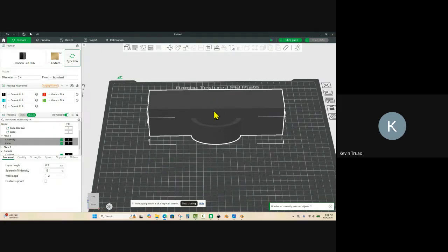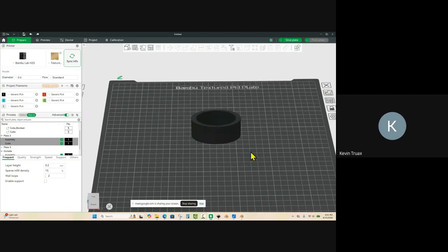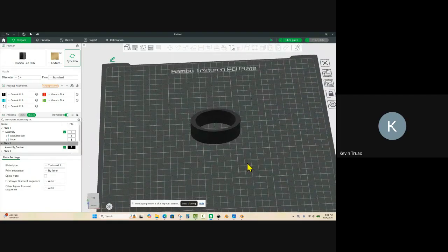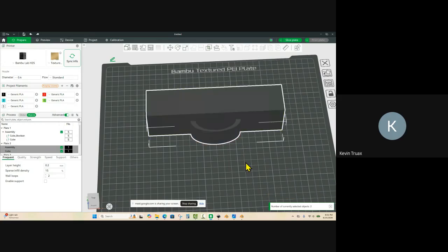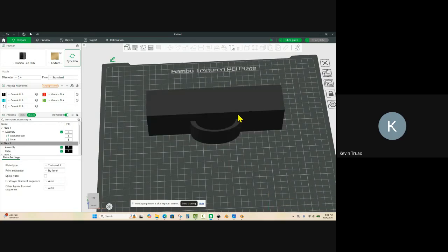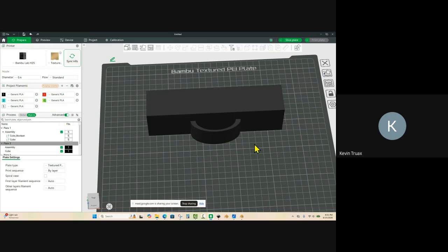All right. So now we're going to do a Mesh Boolean, and we have to flip-flop them because we want the cube to cut the handle, and execute. We got issues. It didn't execute. And of course, we've run into this 1,000 times. So what we have to do is select both parts.